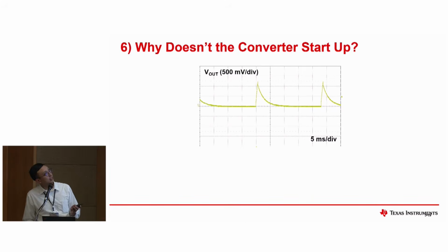Okay, number 6. Why doesn't the converter start up? You can see here this is the output. It always tries to start up, but it doesn't completely start up and it droops down again to 0 and then restarts again. So what can possibly be causing the converter to not start up properly?